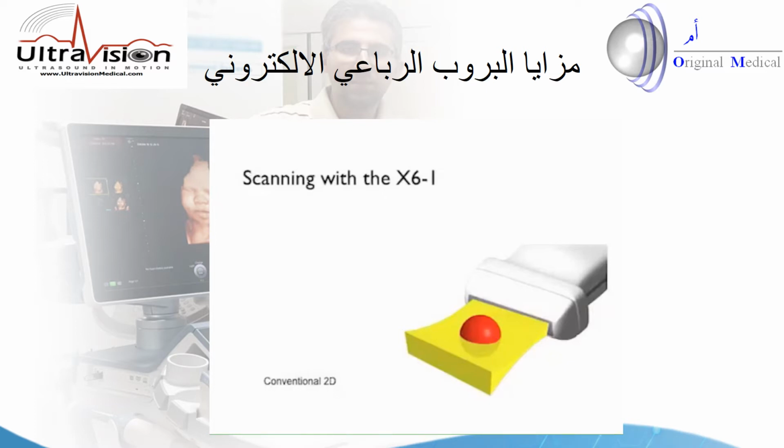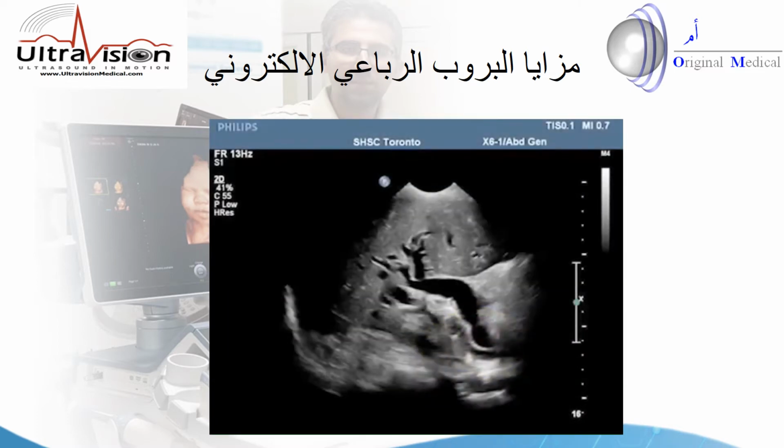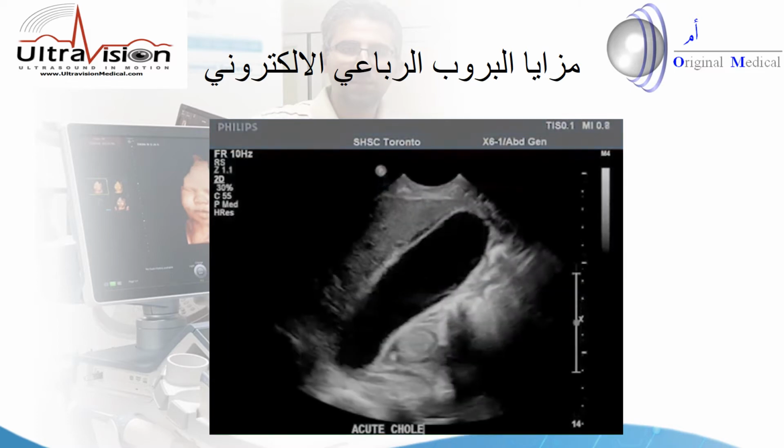Let's look at the modes, and begin with an ordinary B-mode scan. If we were to use a conventional transducer, we're always faced with the fixed elevation focus. The slice thickness is at a minimum level at the elevation focus, then gets fatter towards the transducer and continues to get fatter beyond the focus of the elevation. This is fixed by the lens of the transducer. But with the X matrix, the thickness of the plane is determined and controlled by the beamformer itself. And so extremely uniform images can be made which show contrast resolution to those with which we're familiar with a 1D transducer.